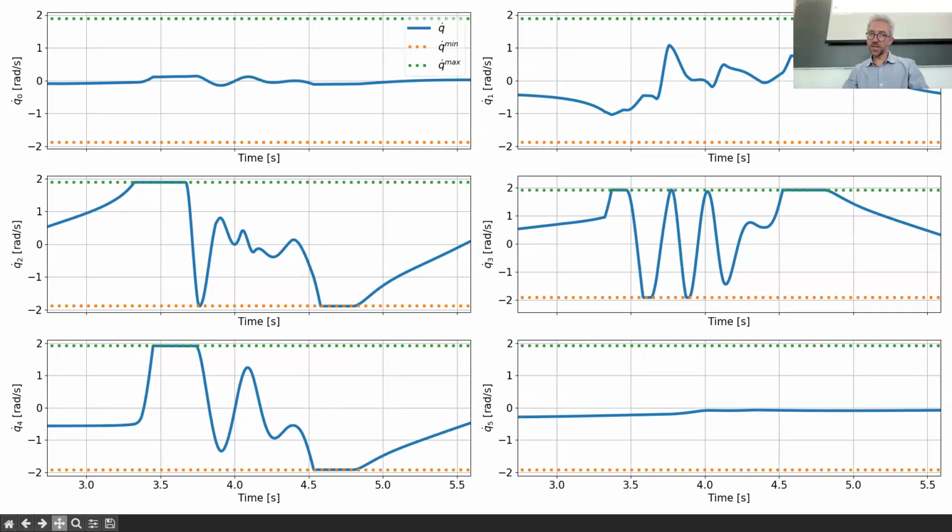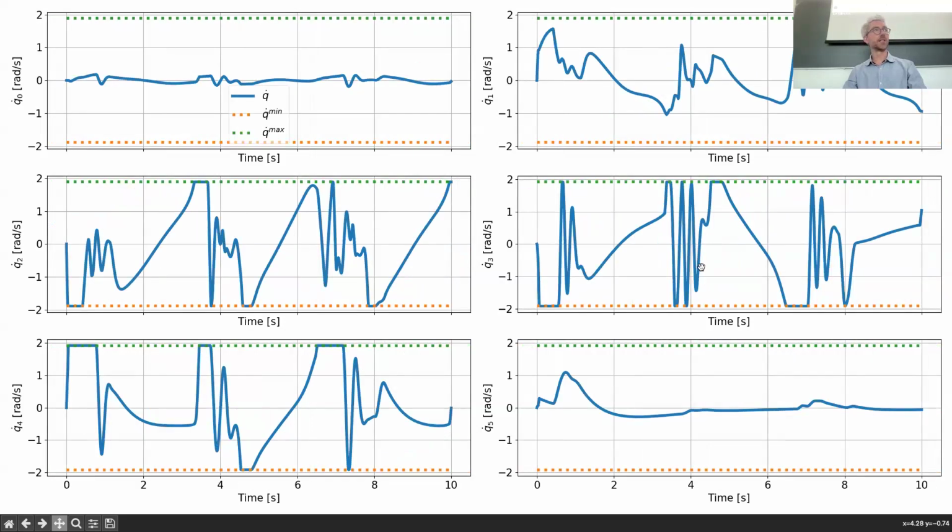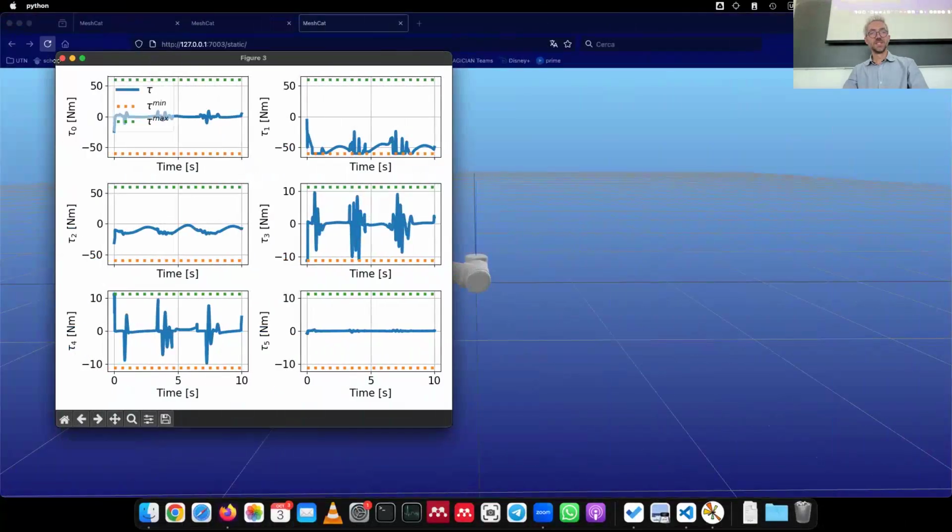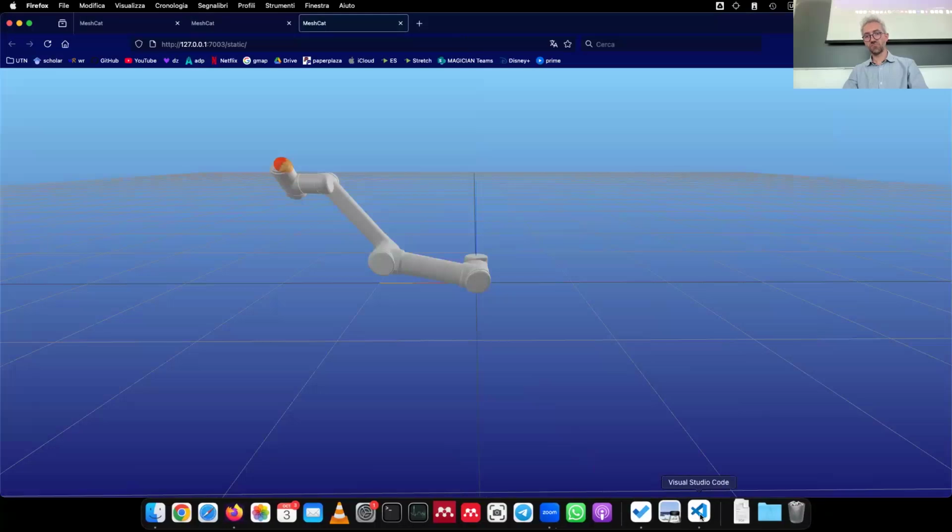So when you see these high frequency oscillations, typically it's a sign that you might want to tune your controller a bit better before testing it on the real system. Question is, how do we fix this? Because it's not violating any limits. The joint velocity limits are satisfied. What are our options? Probably decreasing the gains. Can try that.